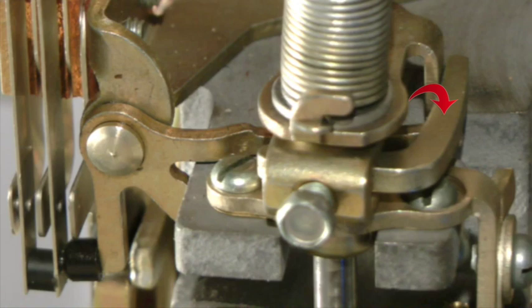When the shaft is in its vertically normal or fully released position, the normal pin rests on top of this pivotable off-normal finger. The weight of the shaft and all of its attached apparatus weighs down the off-normal finger against the tension of these vertical off-normal or VON contact springs. When the shaft steps up vertically by one step, the normal pin is moved up with it and away from the off-normal finger. This frees up the off-normal finger, which can now pivot. This permits the VON springs to operate.